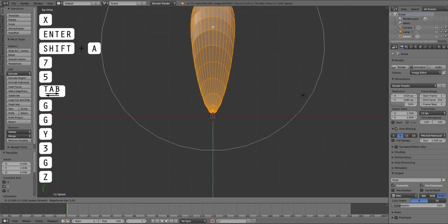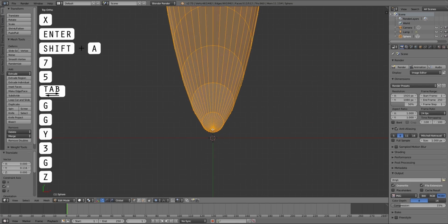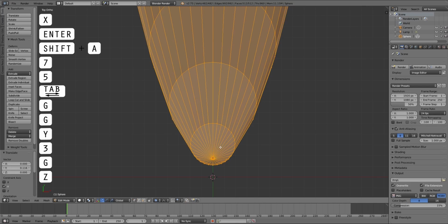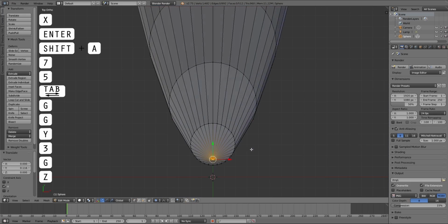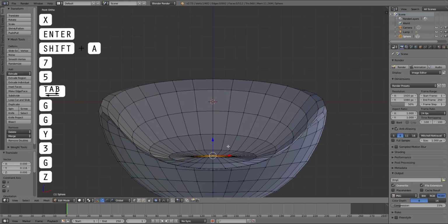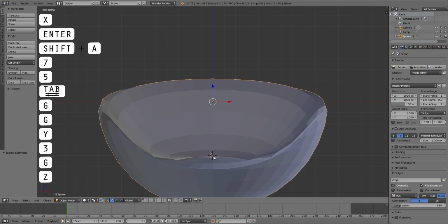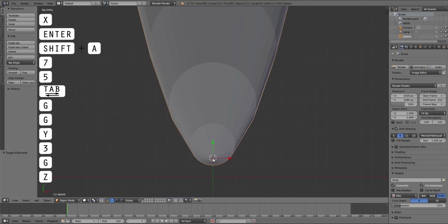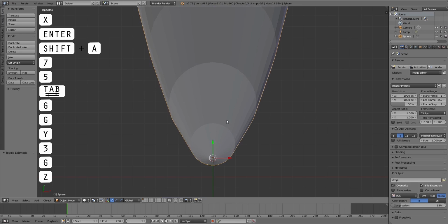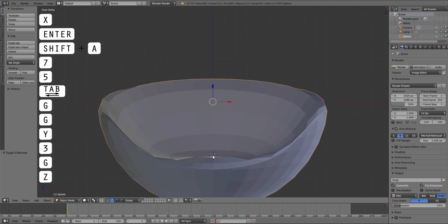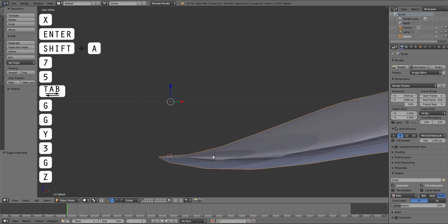Actually, before we do that, we'll set the origin point. Just this yellow dot needs to be at this vertex. So if we just press 1 and go into this view, also be out of edit mode, press Tab to go to edit mode, and just move this cursor along here. You want it just at the tip of where that vertex was. I believe the height was a bit different, yeah. Okay, so with just going between the different camera views, 7, 1, just trying to get the right angle, make sure it's the right depth where the cursor is at.